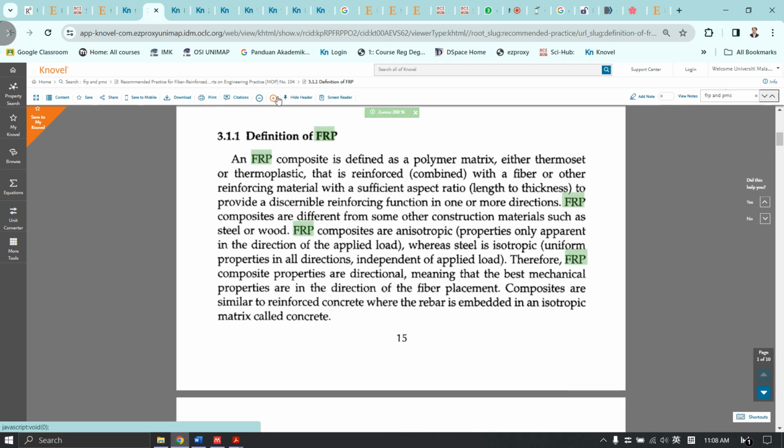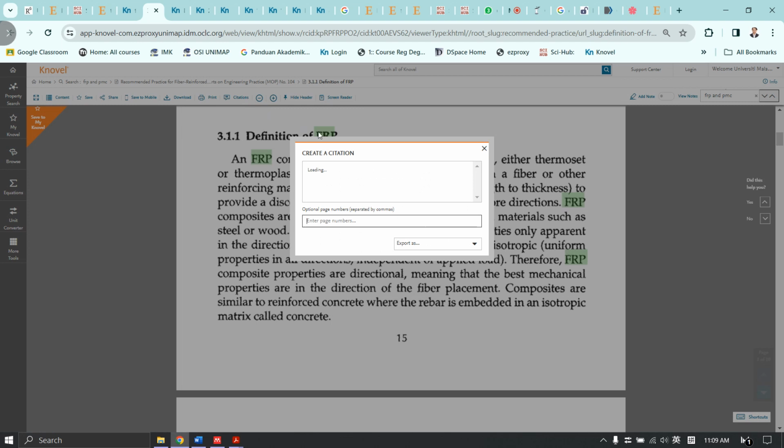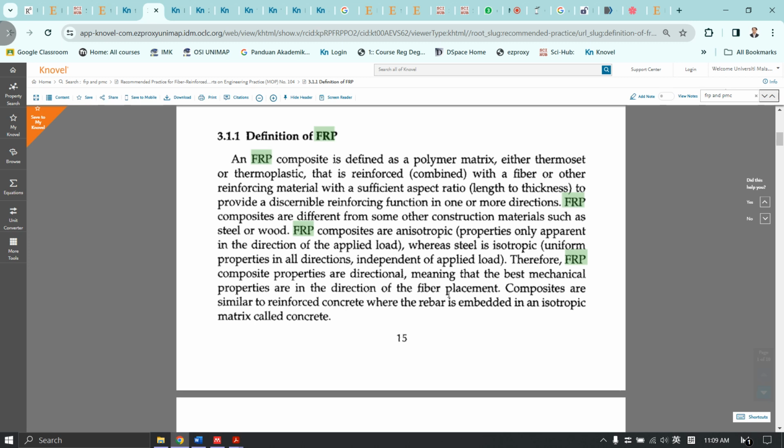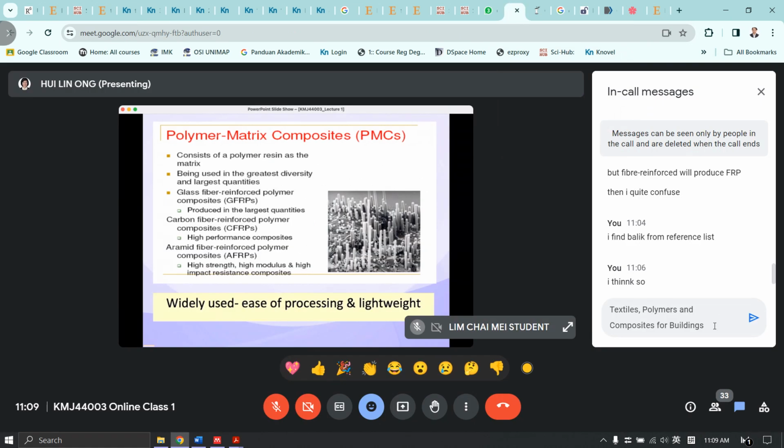Esther, thank you. Now, this is when the fiber pulls out when you do the tensile test for the composite, and this is a fracture surface, then reviewed under the scanning electron microscope. So we see something like this. If the interaction between the glass fiber and the epoxy matrix is good, they adhere very well. They still adhere, so there's no hole. But in some parts the glass fiber pulls out from the matrix, and then it leaves the hole here.